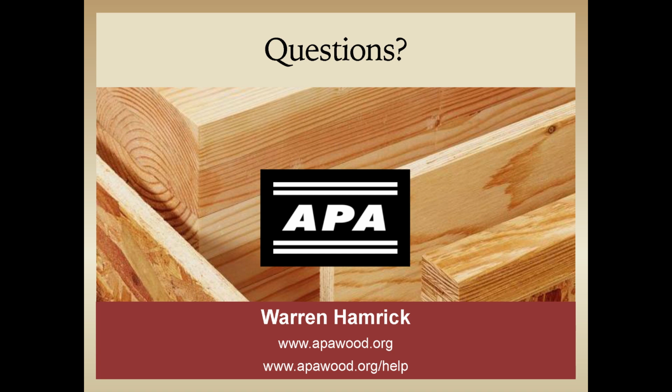Then if you look at a cladding system like stucco, structural wall sheathing is recommended to increase the stiffness of the wall. But to ensure adequate stiffness at either 16 or 24 inches on center, the panel recommendations are in table 24 of the APA Engineered Wood Construction Guide, which is form E30. So it can have an impact that does need to be looked at.